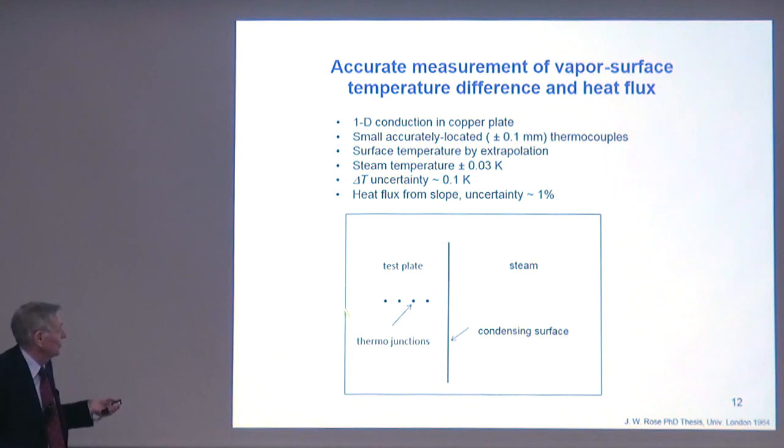Now this was the kind of setup that I used. Here is the steam, here is the test plate. Make arrangements, good insulation, so that you have essentially one-dimensional conduction. These are thermocouple holes. The thermocouples are located to within 0.1 of a millimeter. The surface temperature is found by extrapolation.